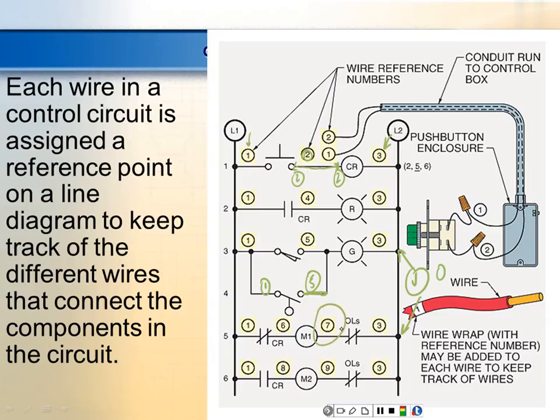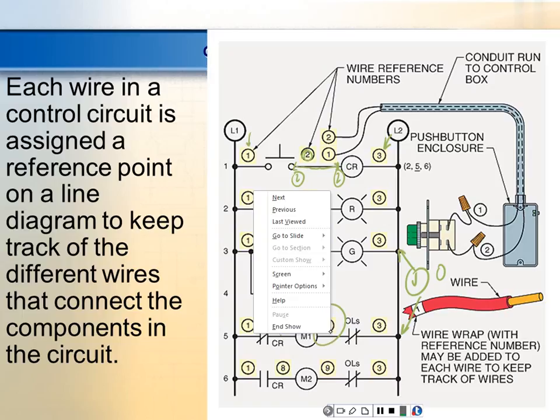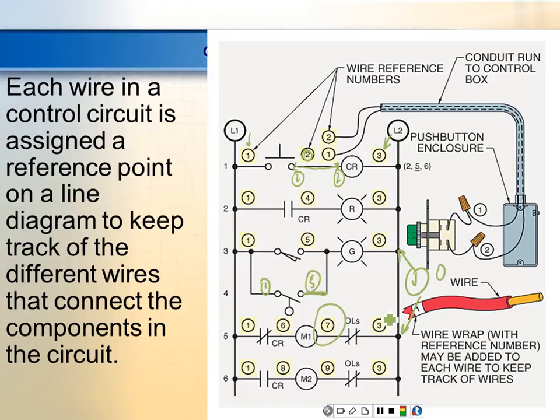This guy here kills people right here. Assign it. Here's a relay. Right on this side I have 6. I go through the relay. I've gone through something. This gets another number. When I come through, this is an overload. This gets a number, but that number's already been assigned what? 3. For L2. For wire number 3. So every time you go through something, it gets a what? It gets another wire number. If it's connected together, they have the same wire number.